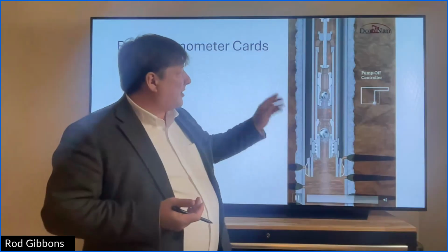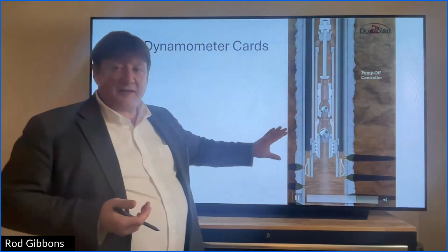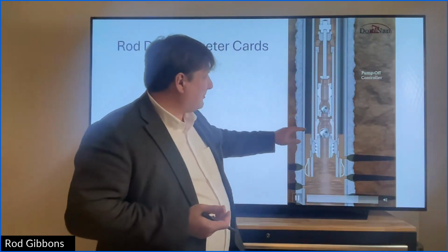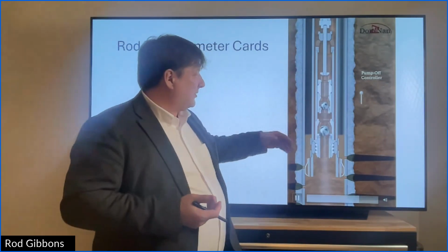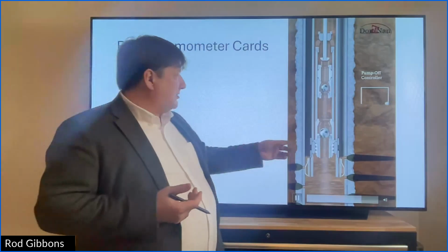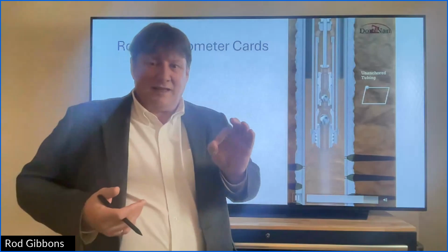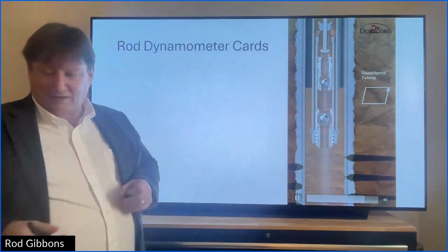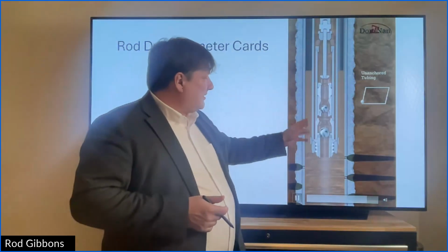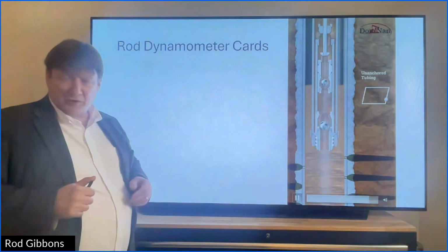So what a pump off controller will do is it'll see when this gets too much, and it'll shut the pump jack down and allow the reservoir fluid to come in, allows the inflow to catch up to what's being pumped out. And so that way you get a more efficient pumping system, and you don't damage these balls and seats, because they're really just little metal marbles that are on smooth round seats. And then there's some, you can determine other things that are going on in the well by different sorts of pump cards. So super useful.